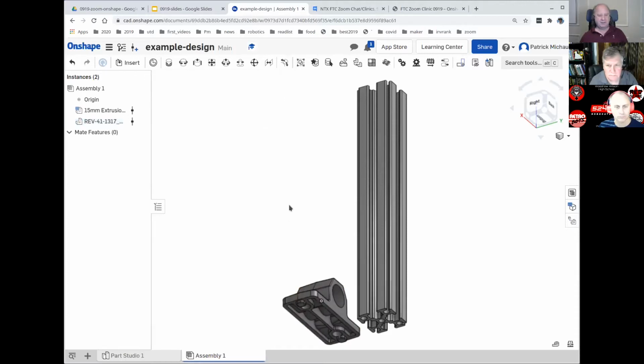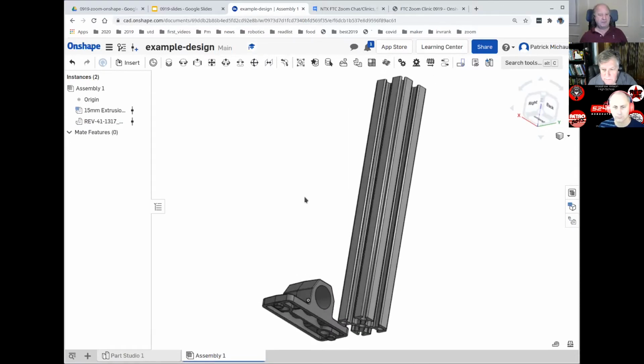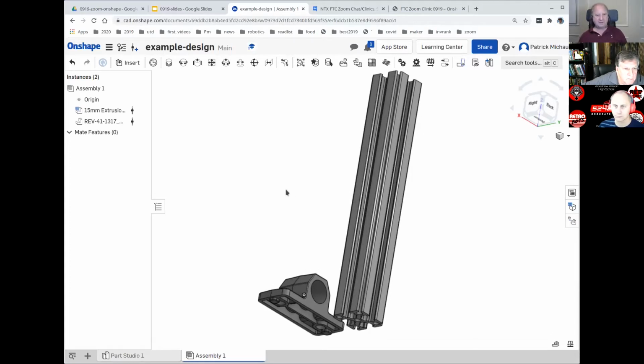And so it's now loaded that into the model as well. The basic operation that we want to do in CAD when we're designing from pre-built parts, in Onshape it's called a mate, M-A-T-E, mate. In Fusion 360 they're called joints, but in Onshape they're called mates. And so what we want to do is to mate these two parts together as if they were being assembled